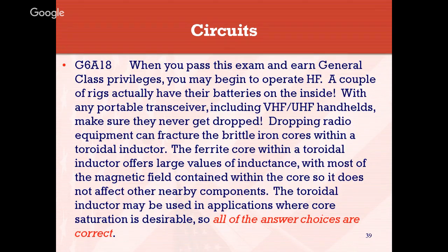A couple of rigs actually have their batteries on the inside. With any portable transceiver, including VHF, UHF handhelds, make sure they never get dropped. Dropping radio equipment can fracture the brittle ferrite cores within a toroidal inductor. The ferrite core within a toroidal inductor offers large values of inductance, with most of the magnetic field contained within the core, so it does not affect other nearby components.